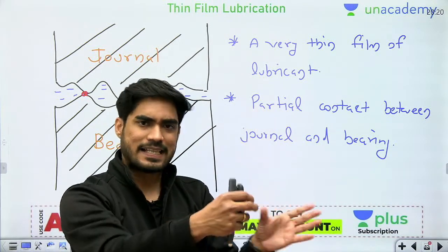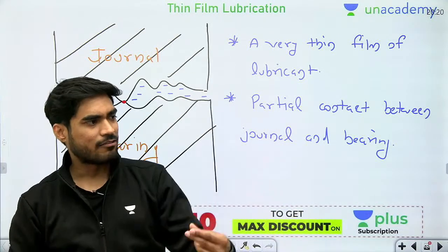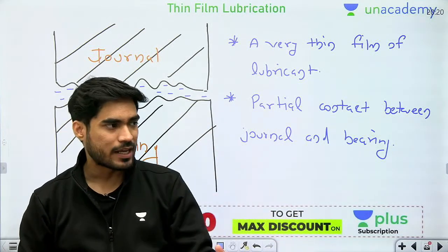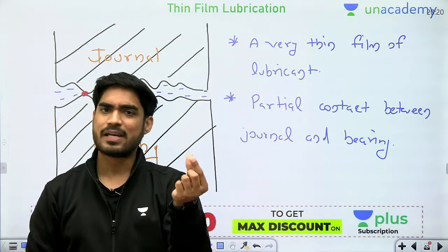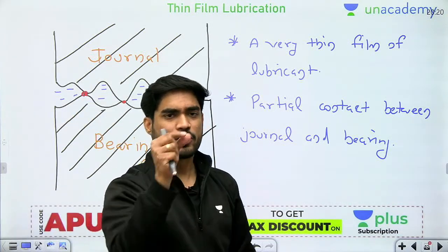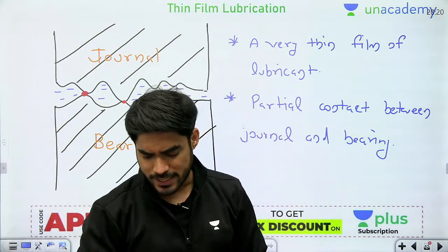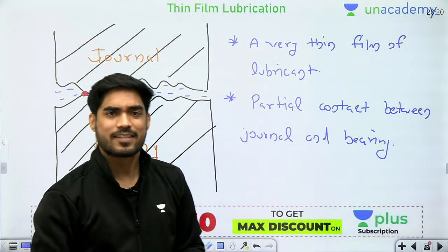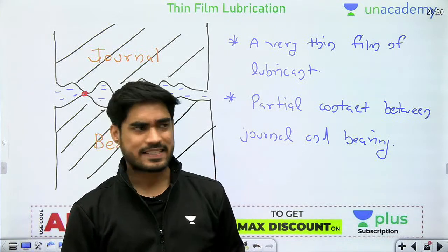of the door. This is like a bearing only, right? When you rotate the door, whatever part is inside that bearing will be like a shaft, rotating inside the bearing surface. So beta, if you put 2-3 drops of lubricating oil in that, then it is a thin film lubrication. Thin film lubrication is used where the speed is less and the load is less.